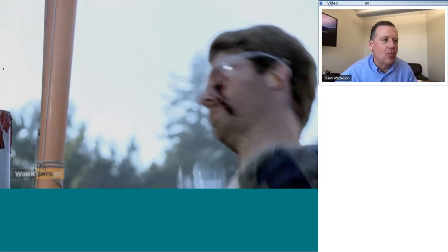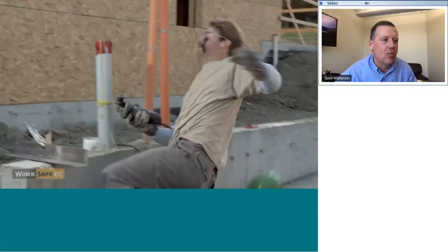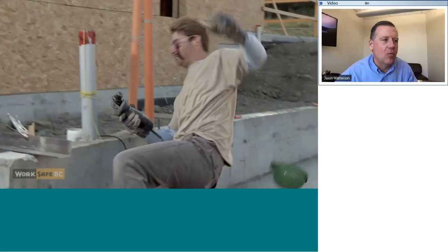The other one is a pair of safety glasses where the person was supposed to be wearing their face shield and they didn't, and they got a splash of material in their face, and you can see where those safety glasses were fogged. Luckily enough, it kept the stuff out of their eyes, but they got a splash on their face and spent some time in a safety shower and had some chemical exposure from this.